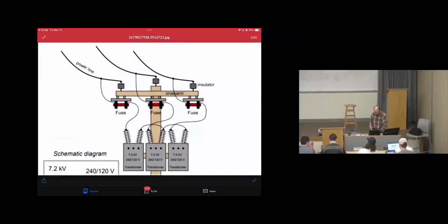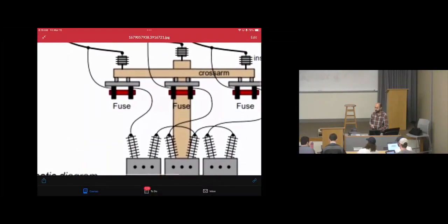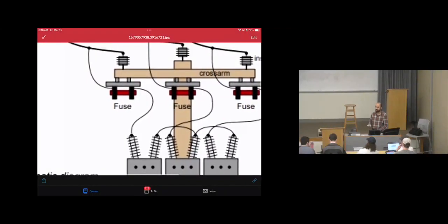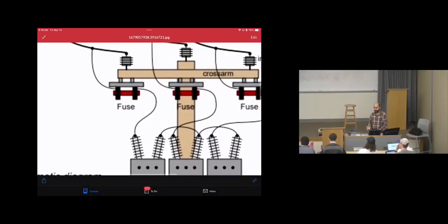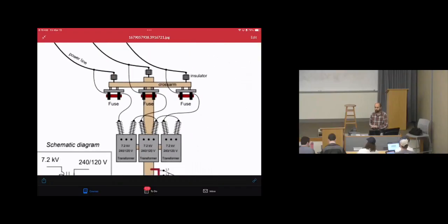This will go to your home, to supply your home. So you will see the power lines. There is a fuse before that. That fuse is used for protection, to protect the utility equipment if there are some damages, if there is a short circuit happening at home and a lot of hazards going on. What will happen? The fuse will detect very high currents, and it will melt, so it will be burned, then nothing will be on. The power will be off to protect the utility side.